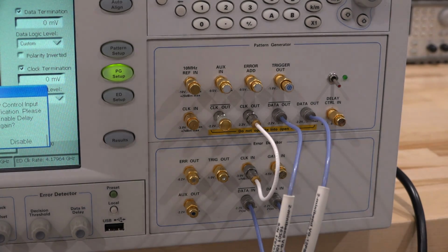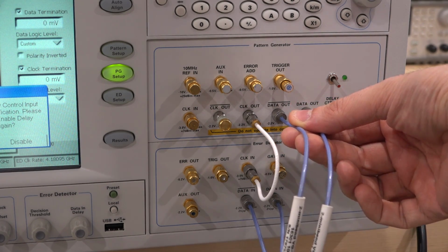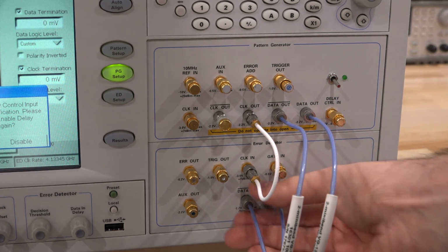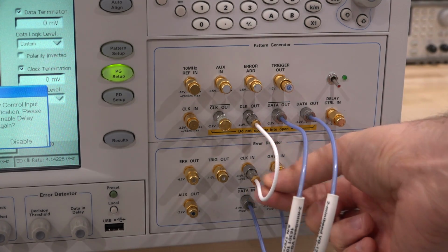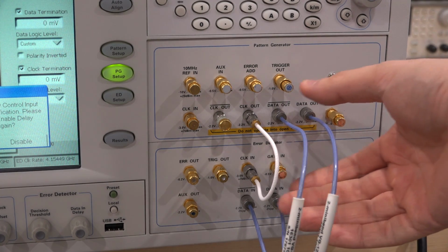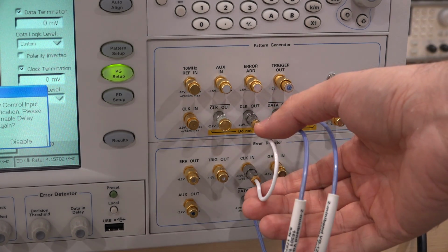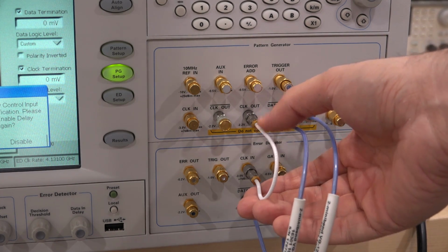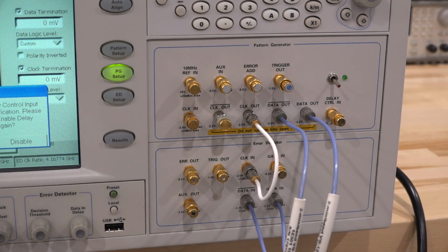And here I'm going to test the error detector. I'm connecting the two outputs of the pattern generator directly to the two inputs of the error detector. I'm also bringing one of the clocks into the clock input of the error detector. The clock is not necessary. This thing does have a CDR, but it's not continuous rate. So there are some gaps in the frequencies it can lock to, and for whatever it cannot lock to, we're going to use the clock as the loop over. So other than that, it looks good. Let's go try it out.